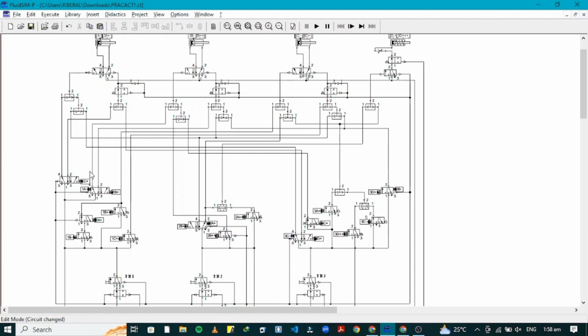So, it uses a 5-way valve connected to actuator A. It has a magnetic sensor that, once the condition 1C+ is reached, or once actuator C is fully actuated from the last sequence, pushes this valve to the left. The direction of the supply then changes to the retraction side of actuator A. In that way, actuator A can now retract.